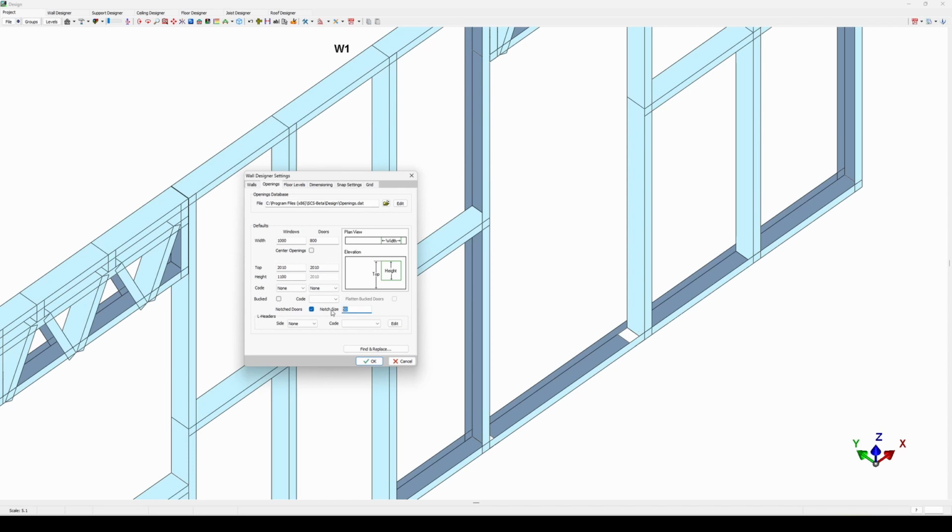The notching tool is a specific size on the machine. You can control what size of notching you'd like to insert on the footplate of your door frame right there by changing the size right there. If it is larger than the punch on the machine, it is going to do multiple punches in that step right there to achieve the size you want.